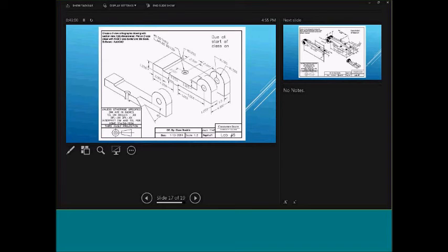This one's starting to get a little more challenging for them. There's a little bit more going on here. This requires a section view to mention that oblique surface that's in the center of that. And this is a good example of my poor dimensioning that's on purpose. For instance, I have the center of this hole dimensioned from where this radius stops right here. And almost every time they'll give me this same 2.5-inch dimension, which is just absolutely wrong. Nobody would ever dimension the placement of that hole where this radius blends into this flat surface.